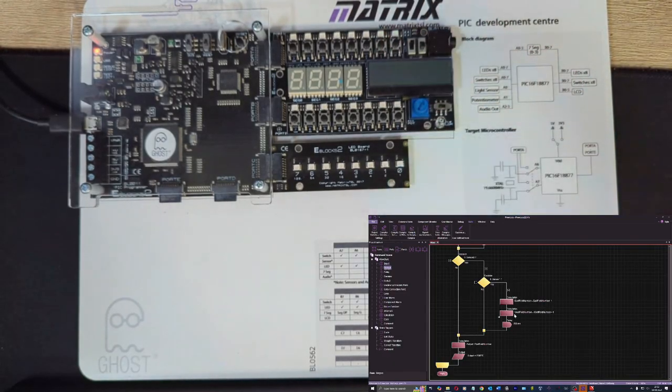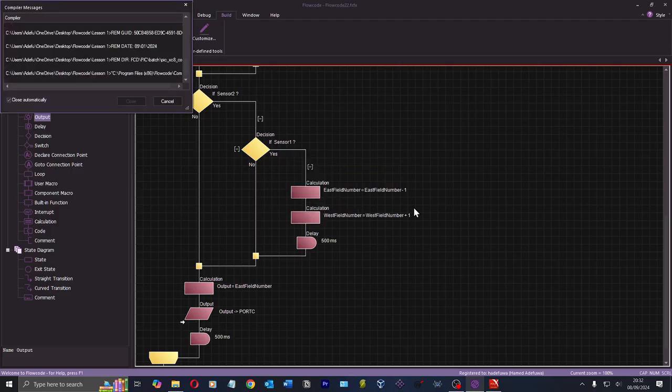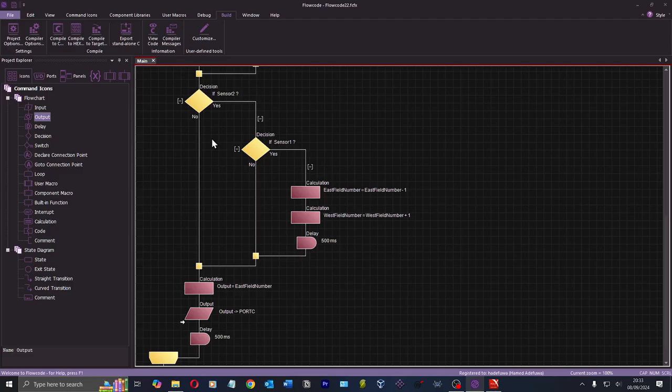So if I press 0, then 1, do we get anything? Oh, I don't have a delay on my output. This is annoying as well. I keep making this really basic mistake. I don't know if that affects things, but nothing worked there. I can't see the value of certain variables live as well. One of the best things about PLC programming is that when you're programming live, you just click on the green glasses and you can monitor all your code live on the real hardware and in simulation.